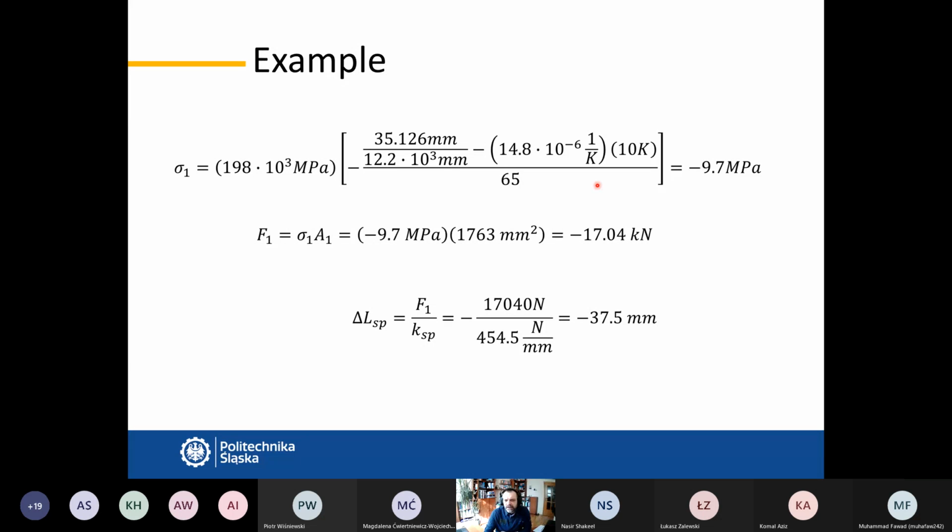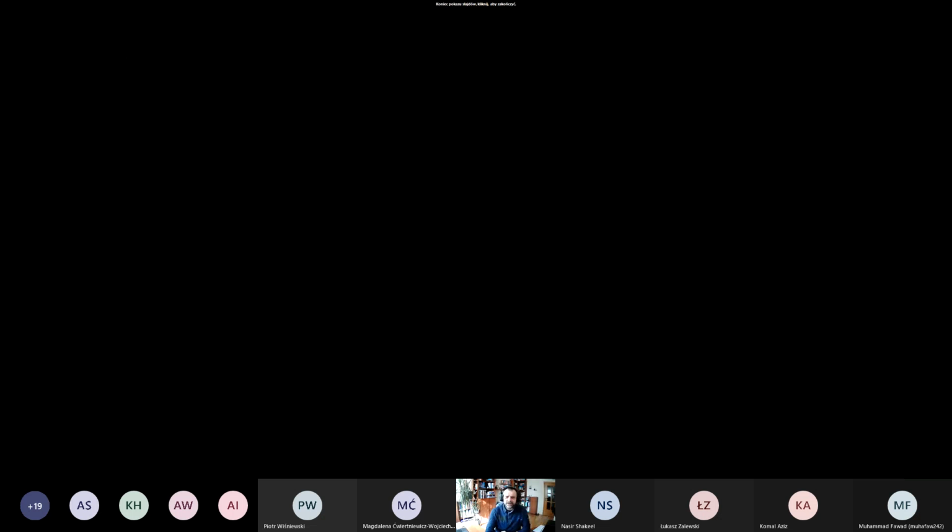Okay, so we see to what extent we can reduce stresses by introduction of either spring element or thermal gap. This bellows, of course, if we would provide here a thermal gap, there would be a leakage. So there would be, let's say, a heat loss in such a case.